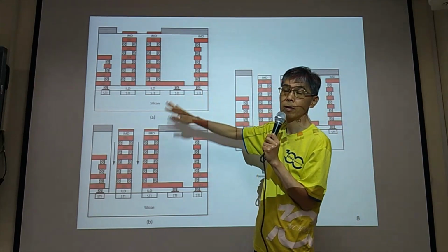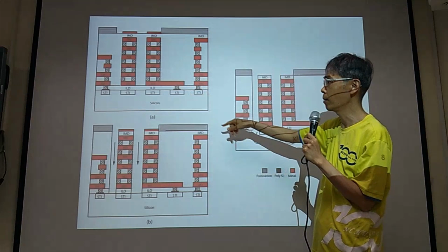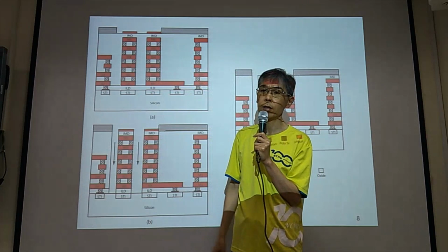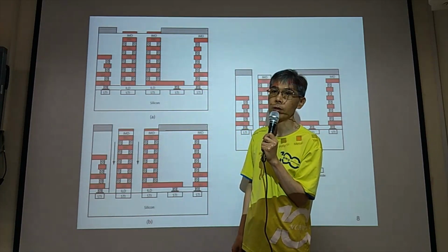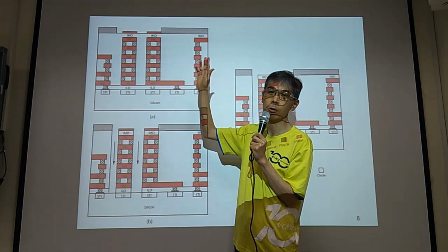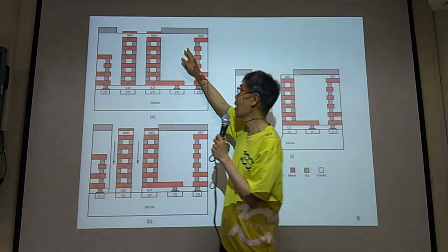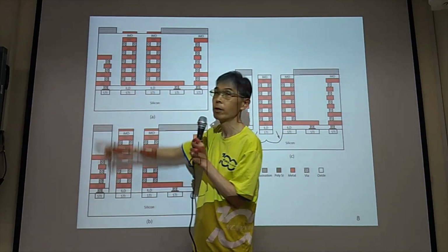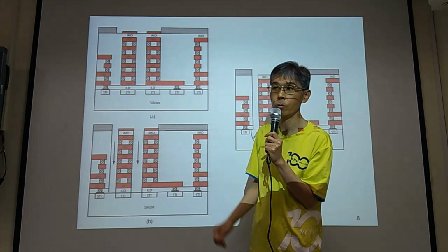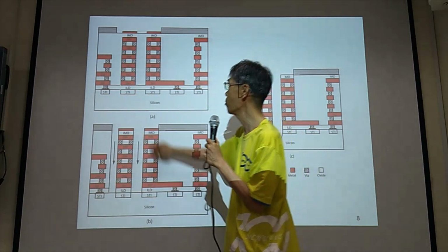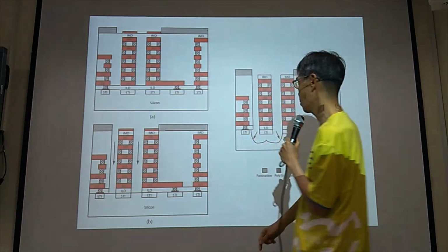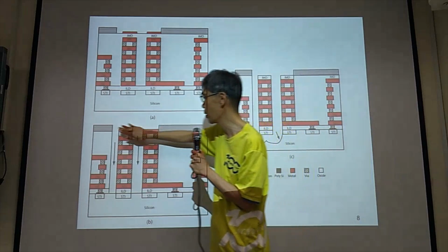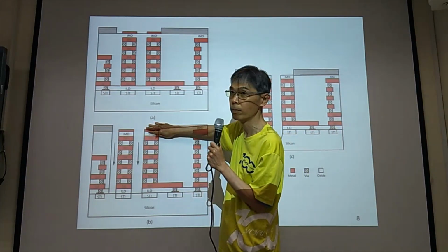After CMOS, the transistors are protected by amorphous material, oxide or PSG, some oxide material. But in order to make the sensing structure, we need to remove the oxide here. So this is a protection area, and we remove the protection material here.